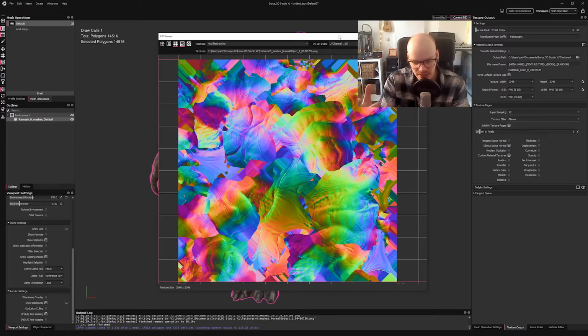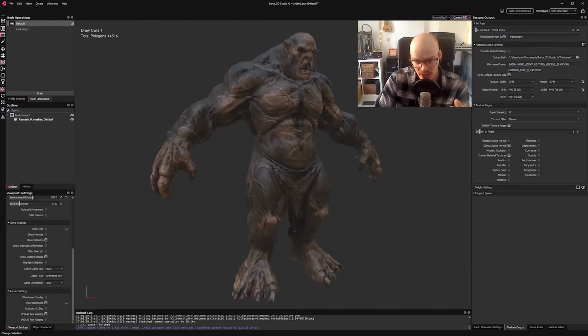So what InstaLOD did here is it generated the object space normal map for the silhouette and the geometry, then took the input normal map, the tangent space normal map, and combined both of those textures together, and then had to recalculate those normal maps so that they would fit and work on this model. And that is an absolutely incredible feature. As far as I know, no other baker is actually able to do that.